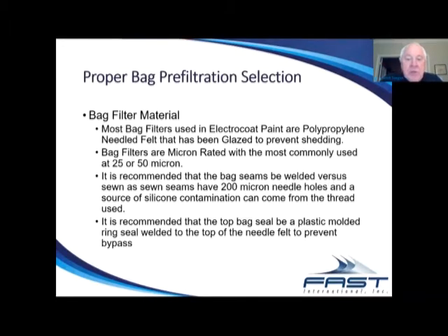We also recommend using a welded seam versus a sewn seam. The reason for that is that the needle holes put into the bag by sewing it are 200 microns in size. And so we have a 50 micron or 25 micron bag with a bunch of 200 micron needle holes. The second thing is, in my experience, one of the sources of potential silicone type contamination has come from the threads they use to sew the bags.